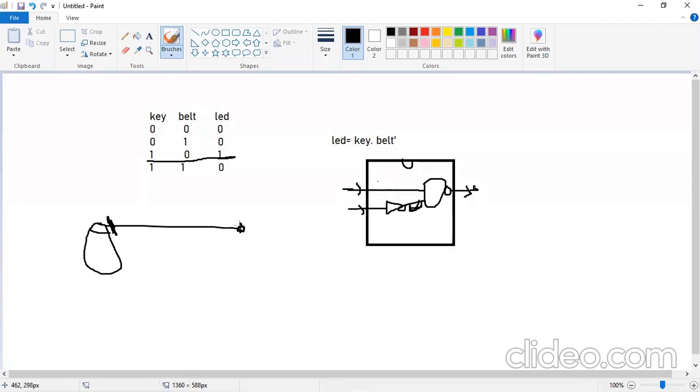So a wire is not a storage type. You can only drive the value on a wire, continuously, and you get the value as long as you are driving it. In case of reg, it is like a storage thing.